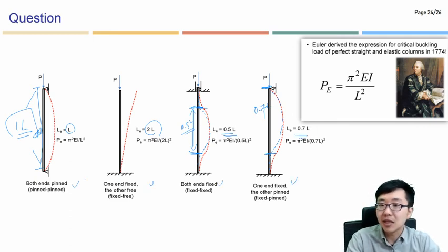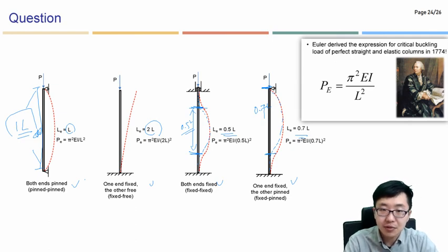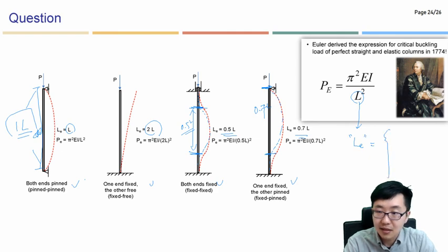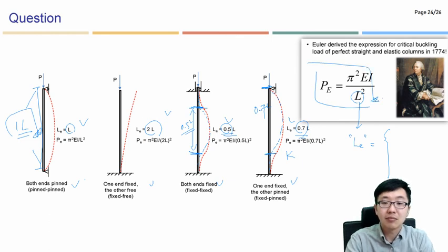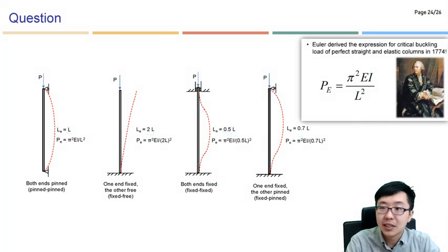So that is the main point, and based on this length information, we can simply substitute it. Actually, this will be revised to effective length, and that is like that. So just simply change the coefficient here, we call the K, so that we can still predict the elastic buckling force or elastic buckling strength as well.